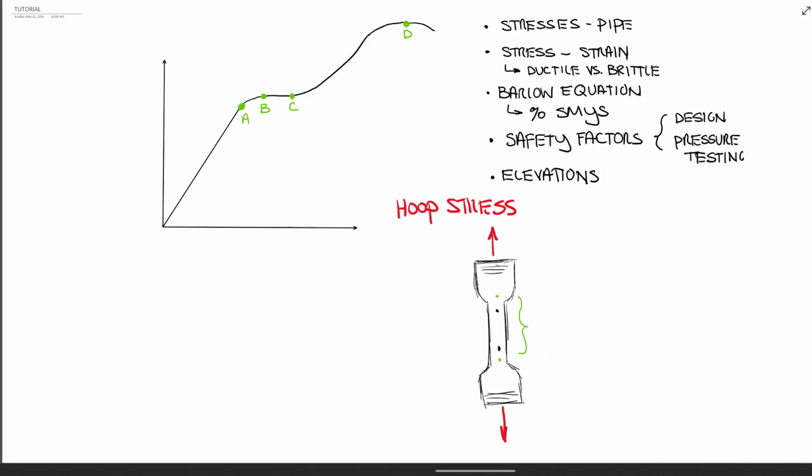And then they can basically calculate this, the general equation. It's not very complicated: length final minus length initial, all over length initial, and then times 100, and that'll actually give you your final percentage. Overall, anything 5% elongation or greater is considered ductile.